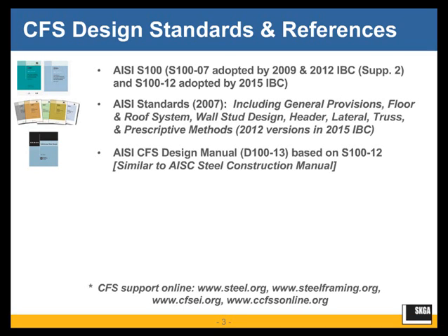For instance, if you have a typical cold form steel shape and you're looking for the design strength of that shape, you can go in and the nominal values are shown for particular shapes and unbraced lengths. And you can go in and determine capacity multiplied by a resistance factor to get an LRFD value, or divide by a safety factor to get an ASD value. So very helpful. Kind of speeds design along.